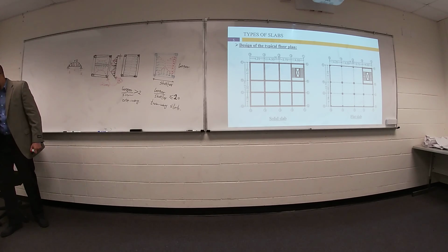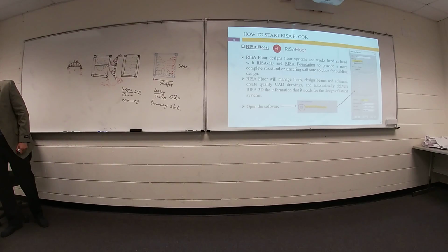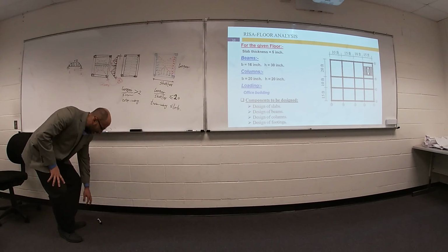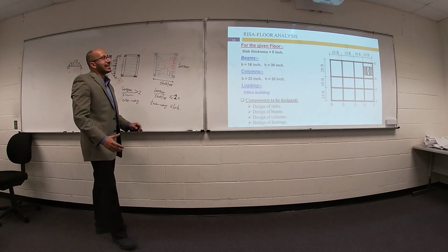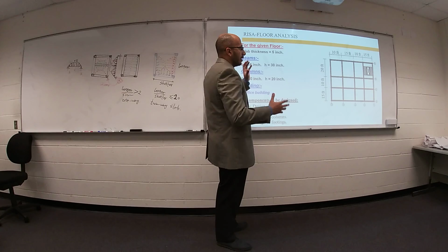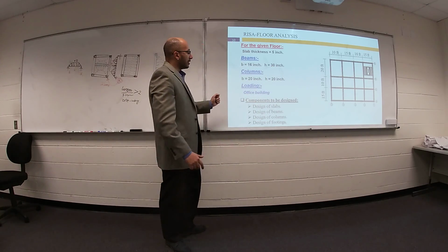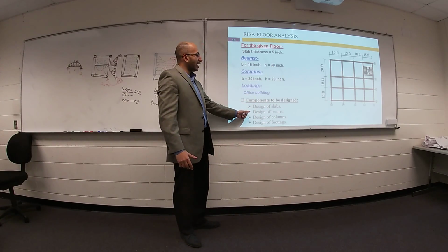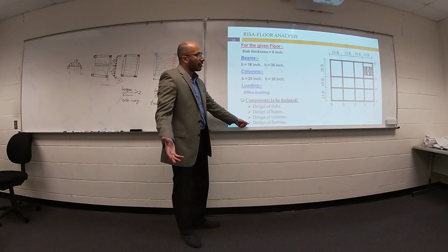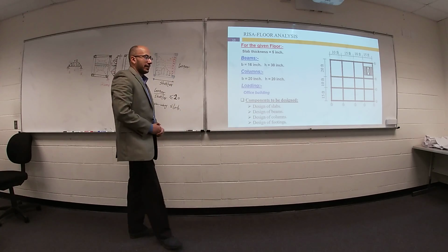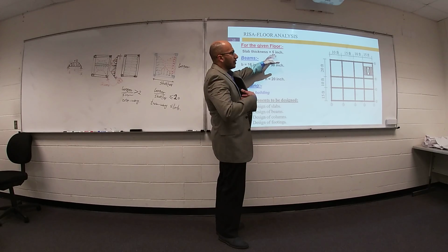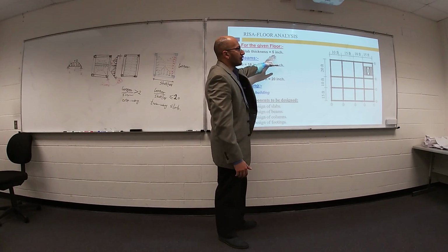So right now we are going to start to define this plan in software called RISA Floor. The main purpose for this modeling, we need to design slabs, we need to design beams, we need to design columns, and finally we would like to design foundation like footing. Okay? Your slab thickness, I assumed my slab thickness equal 5 inch.